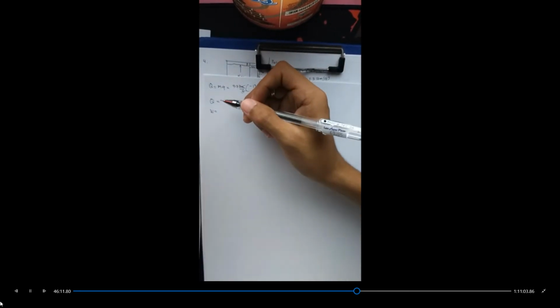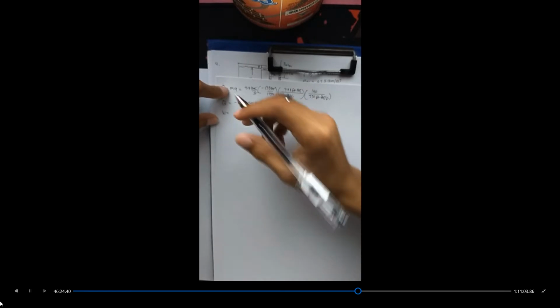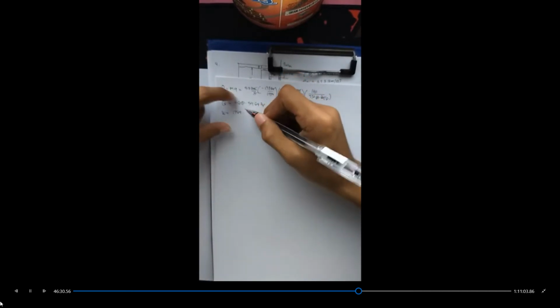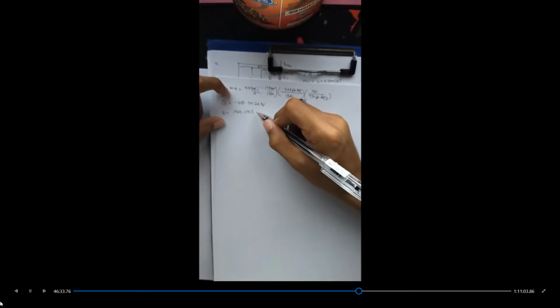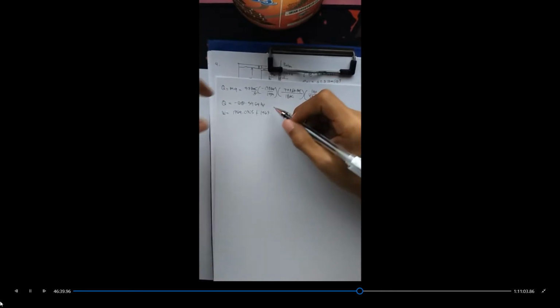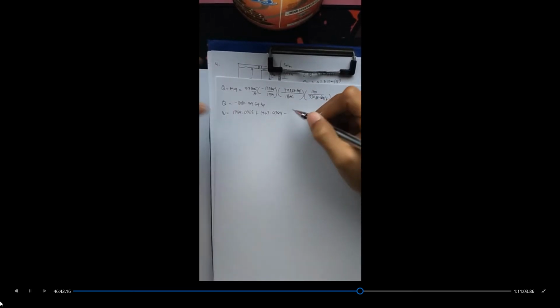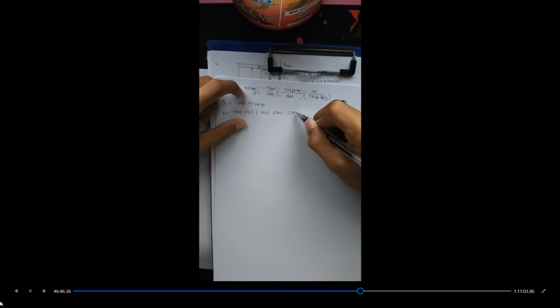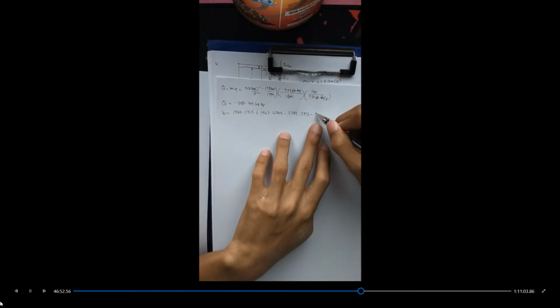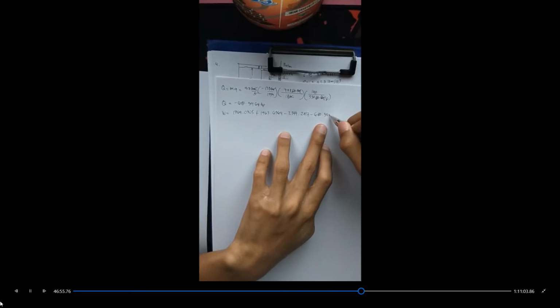Work is equivalent to our general equation here: U1 minus U2 plus EF1 minus EF2 plus Q. Substituting the values: U1 minus U2 is 1769.0305, our EF1 is 1963.6364, our EF2 is 2549.2817, and our heat is negative 680.3964.